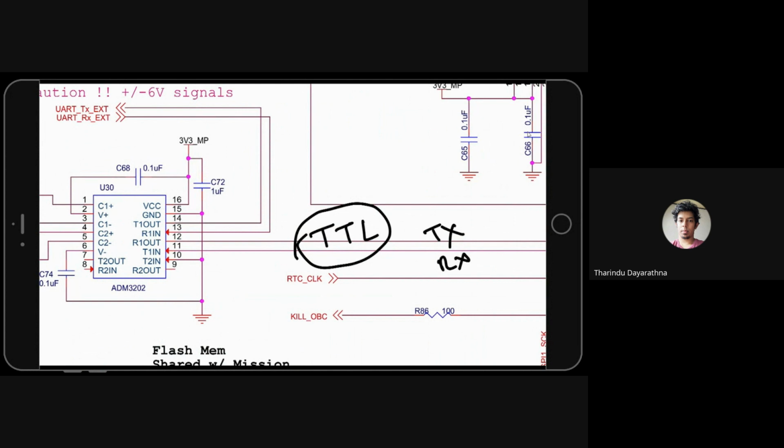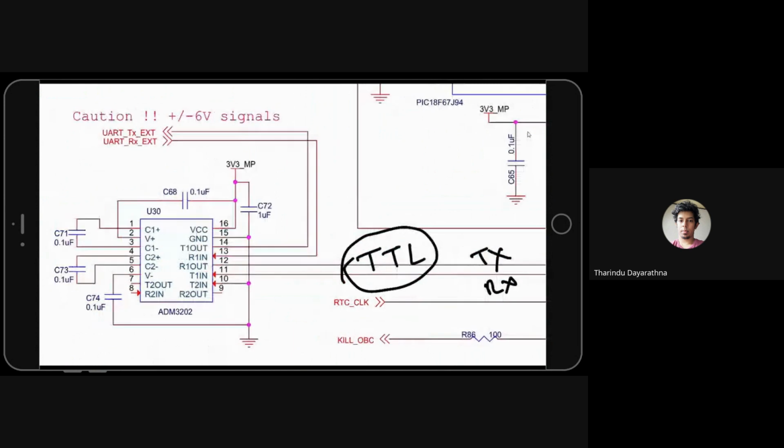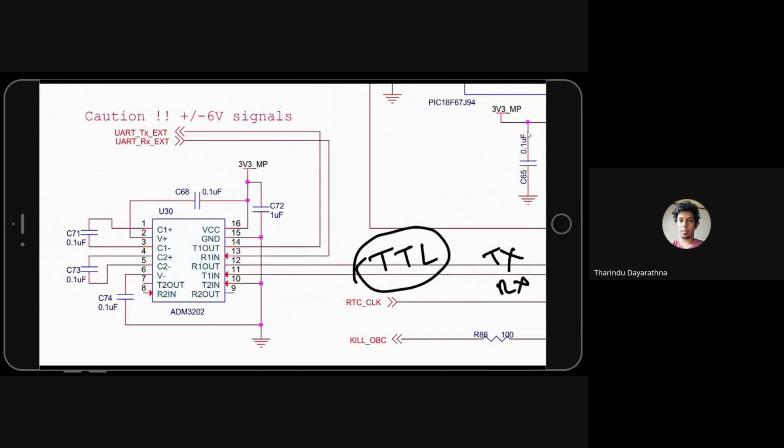You need to buy that serial reader. It's a different one. If you connect the normal serial reader, this voltage will destroy it because it has negative 6 volt also. It happens many times. People did not know and connected it.